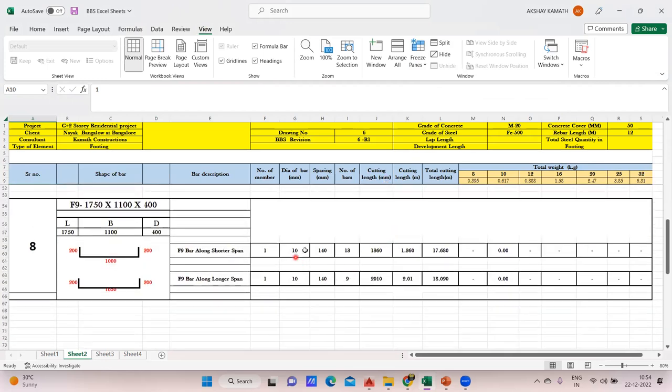Okay, fine. 140, 140. So cutting length, this is cutting length. Cutting length will be how much? Very simple: 1000 plus 200 plus 200. Now, how did you get this 200? You know, 400 minus 50 we did, and whatever answer we got, we took 2/3 of that. So that is why 200 is coming. Okay, great. So cutting length we understood: 200 plus 1000 plus 200.